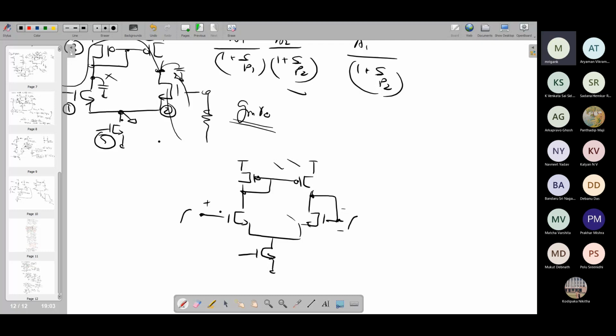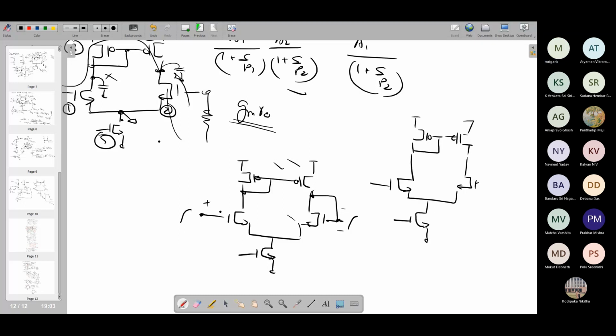This one I would like to cover, maybe another small thing, if this is clear. Another thing is input swing or input common mode range. So in this case, how do we find out the input common mode range? We have discussed this with respect to the fully differential amplifier. Here the condition is different. Why is it different? Because the two sides are not symmetric. One side you have a direct connected load, on the other side you have a kind of current source load.